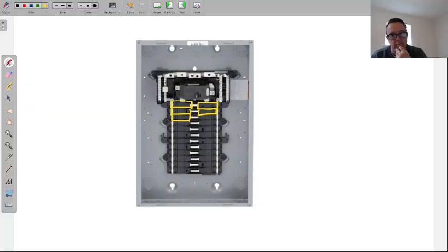So you can put all the batteries on one circuit? Well, let's think about how we're going to structure this. Let me see how I explain this first. There's a rule of thumb that we use out in the field for how many receptacles we're going to put on a breaker. But first, let's put that into a situation, because situations are different in all of electrical, meaning I could be dealing with a commercial building versus a residential. So let's say we're in a house. We're going to lay out all these receptacles.